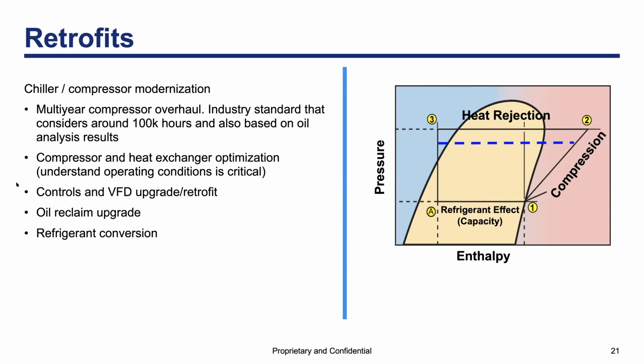Aerodynamic components are evaluated to increase capacity or better performance, at partial load, or maybe both. Once again, adding or considering a VFD is a great addition. But now, since refrigerant conversion is usually followed by capacity loss, check and confirm motor limitations about mostly output power and rated load amps or RLA.